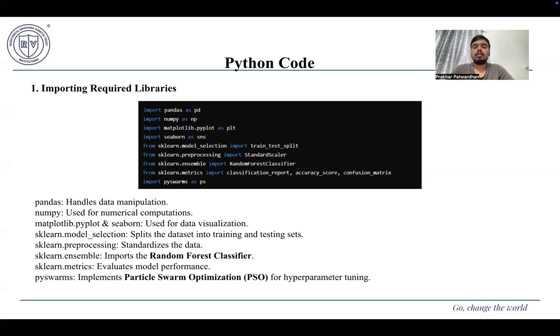Second is calculating the signal to noise, S/N, ratio, where larger is better for strength stress ratio, and smaller is better for volume and weight. I use particle swarm optimization to find the best gear parameters while ensuring robustness. So what's new? In Taguchi's orthogonal array, it simulates 9 test cases per parameter set to measure robustness. The signal to noise ratio minimizes the sensitivity to manufacturing variation. PSO optimization finds the best gear parameters using robust performance metrics.